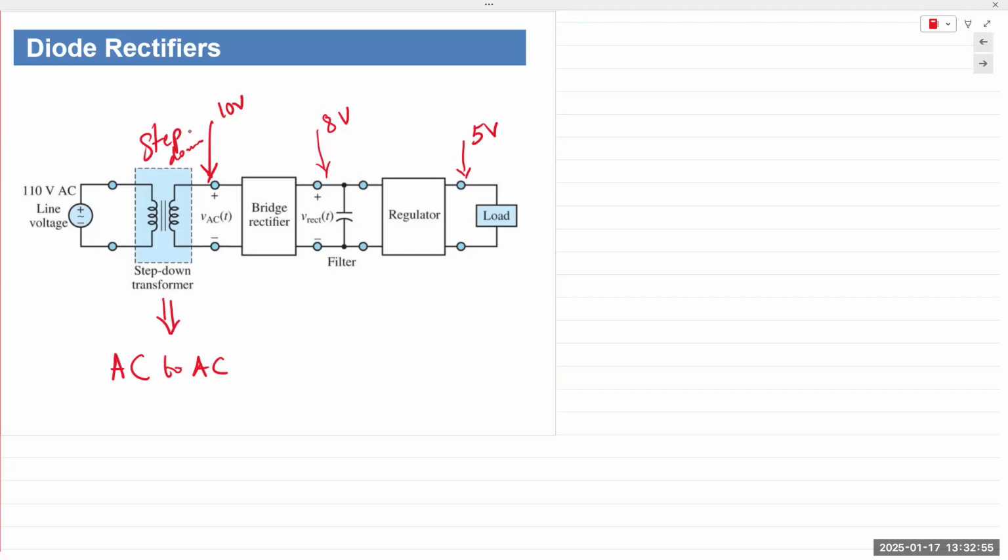Okay, just an example. But again, everything that we use is DC, so it incorporates a power supply circuit like this inside it. Now, in the old days, we used to have these transformers that would be about this big in size. So if you've ever seen an older power supply, it will be far heavier than what you use nowadays. Nowadays, you have these mobile chargers. They have the exact same principles, but they have high frequency transformers. So we are able to squeeze down the size, but the operating principle is still the same.